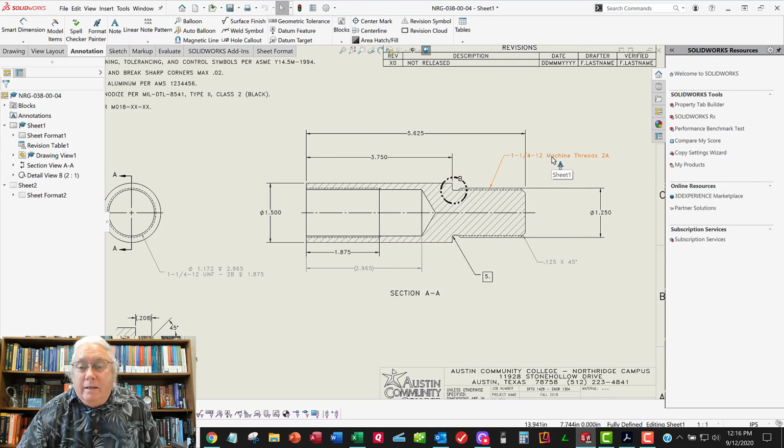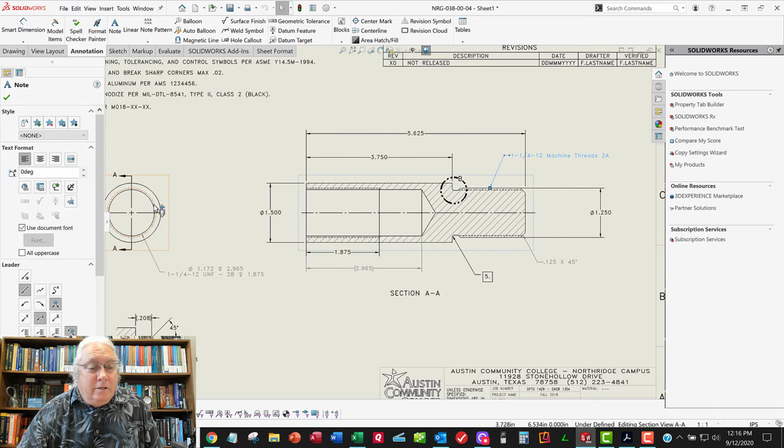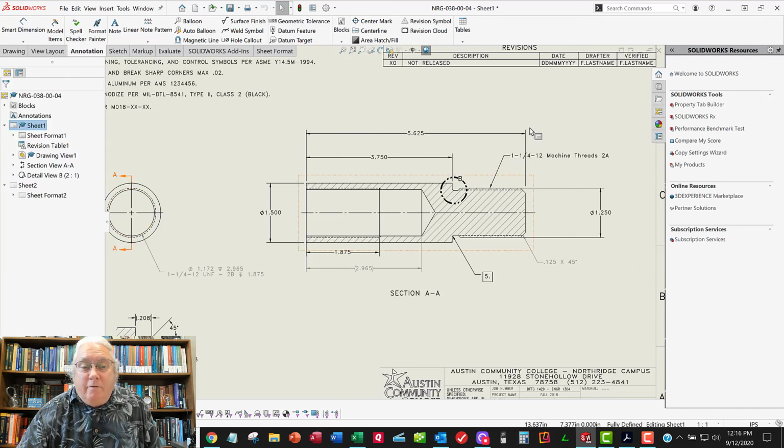Bummer. That must do a one-shot thing at the beginning. And so here's the game you need to play. Before you do anything with your drawing, go into the model and make that change. And I believe that at that point, when you make that first view, it'll pull it one time from that note in that cosmetic thread feature.